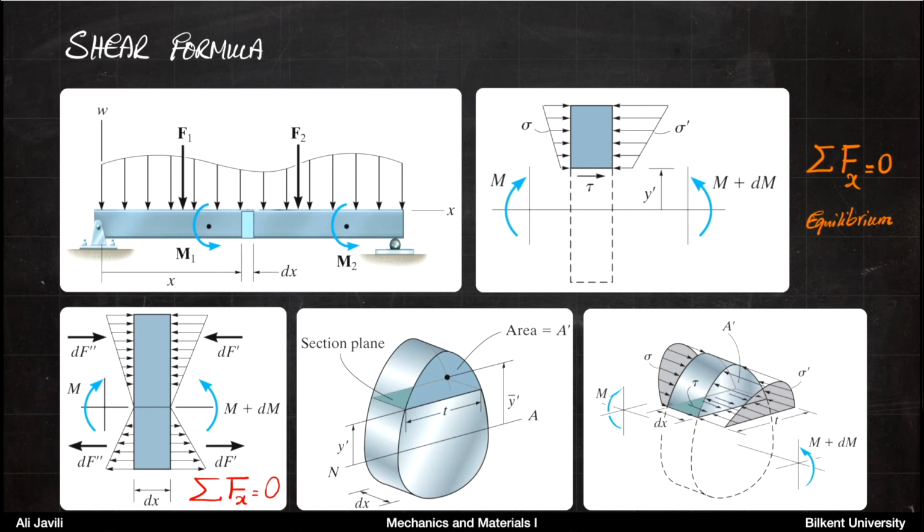And we have also learned the relationship between stresses and moments for such problems. That would be our flexure formula. If you remember, we had sigma equals My divided by I, well, with a minus sign maybe, because we wanted to show that it is compressive if y is positive, and y is the distance from the neutral axis. So we have learned this one before.